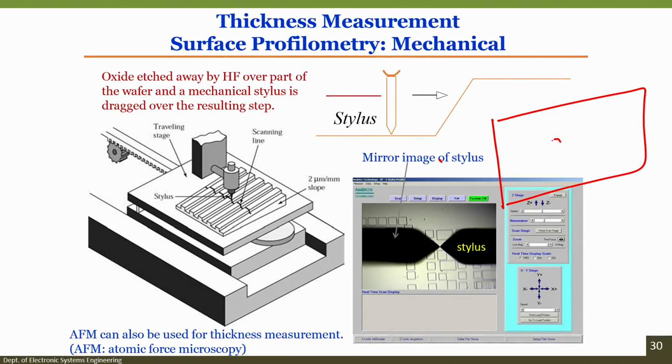Second idea is that, if you see the screen, if I have the wafer, right, I am drawing a wafer on the screen, and if the silicon dioxide as I am growing is uneven like that, okay, how would I know what is the roughness of this silicon dioxide? This is silicon dioxide. So, to understand the roughness of the film, I will scan this film again with a stylus profilometer, and I will understand what is the roughness of the film. All right. So, this can be used for many applications.